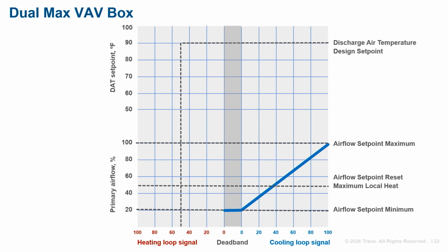When the cooling load has decreased to the point where the VAV damper has reached the minimum airflow, the zone temperature is allowed to drift downward through the deadband between the cooling and heating set points, while the airflow is maintained at minimum. If the zone temperature drops below the heating set point, the reheat coil is modulated to maintain constant discharge air temperature. As the heating load increases, the discharge temperature is reset upwards while the airflow is kept at minimum.